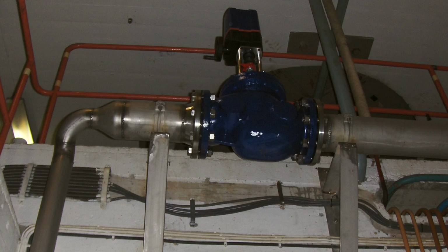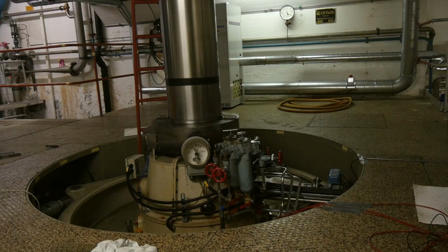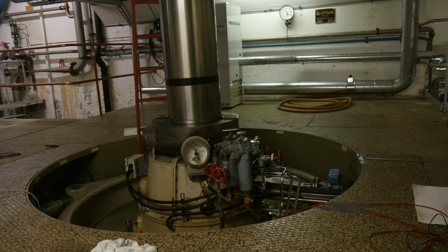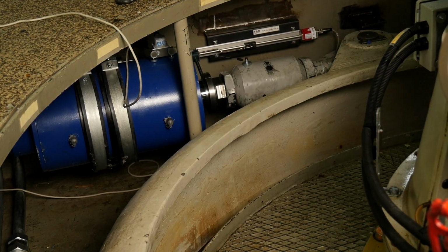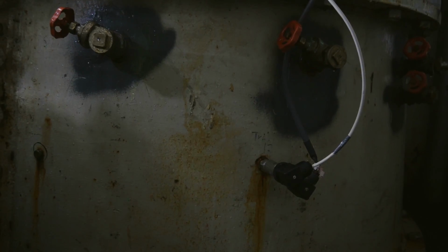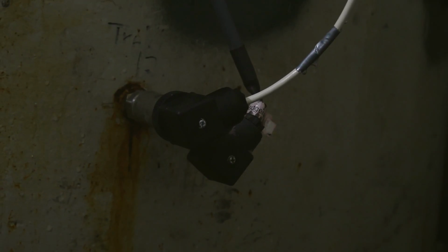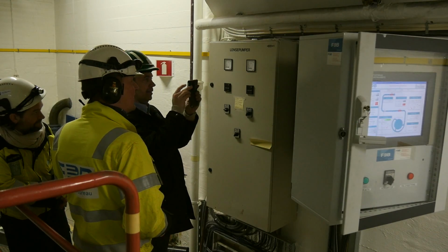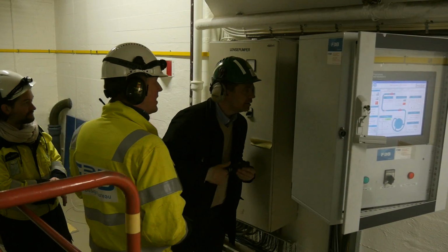Secondly, it is imperative that the injection of the water is regulated. This is done according to the flow, or in fact by the guide vane position. Also, detected pressure pulsations have to trigger the system. One should be able to consider the system as a standalone product, which is why the auxiliary systems were imperative to develop.